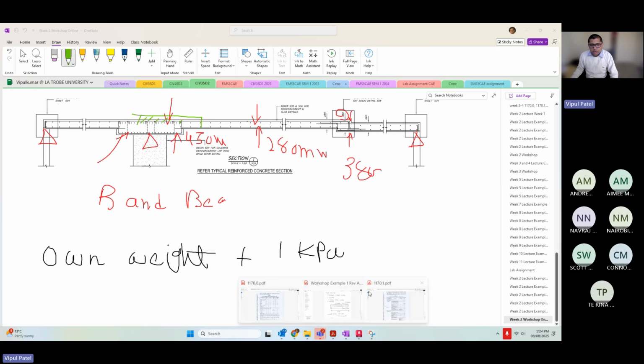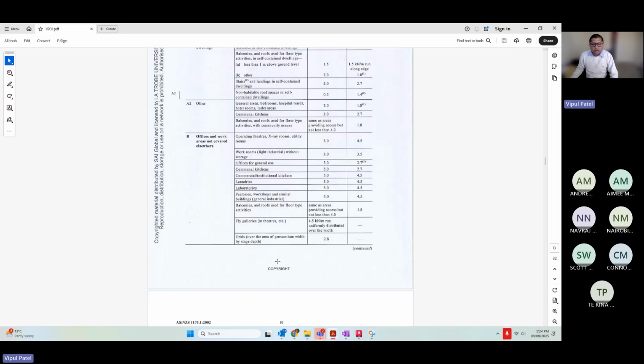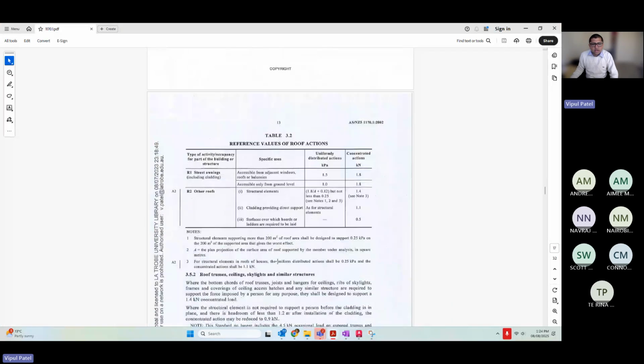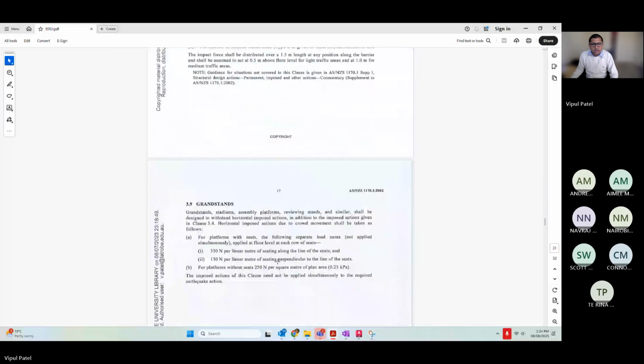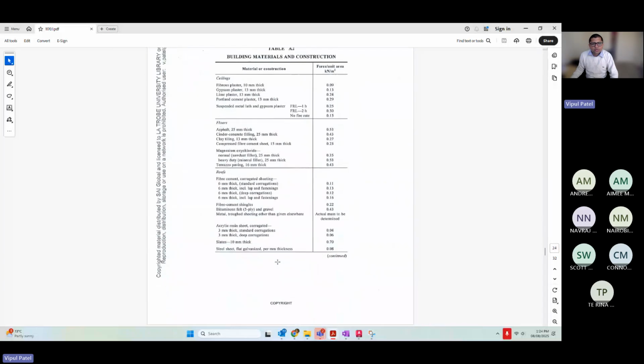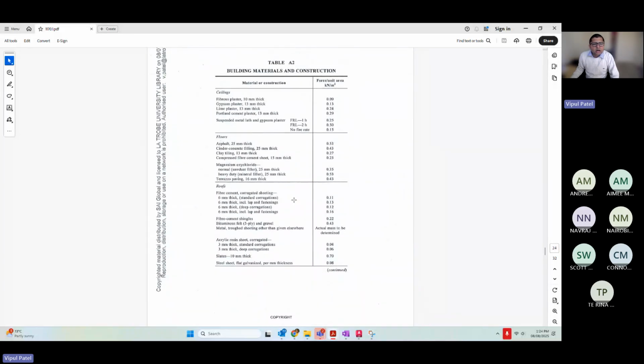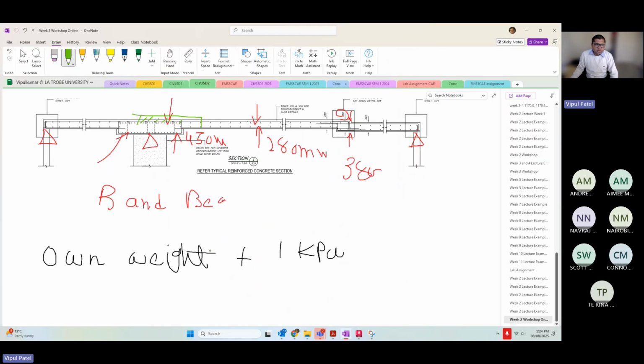Someone once said, how about you go and pick this terracotta paving and something like that, right? Because they said I'm not happy that you put 1 kilopascal straight away without any of this. Why don't you just take 0.13? No, look, these slabs are quite heavy. This 1 kilopascal will be extra material that we're going to look into.